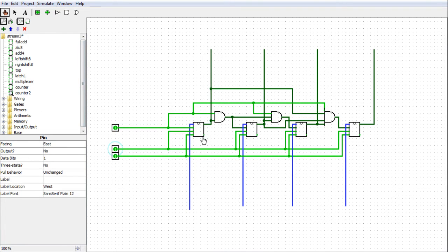Counter register. Now, the other thing is you want to be able to load parallel values into the counter, which is very important. For example, if you're executing a jump instruction, you want to be able to load the value of the new address into the instruction pointer. And that is just done. Nah. Let's just show it quickly here. Might as well.